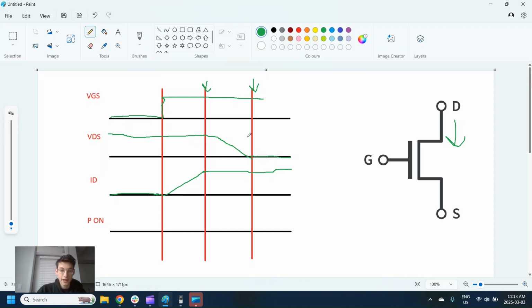So here we go. You can kind of see where the power losses might come from. Anytime we have the voltage positive and the current positive, we're going to have some power being dissipated across the switch. So every time in here, there's going to be some power loss. We're just multiplying these two to get the power losses, which will look exactly like that. So that's what it looks like, and we can walk through what the values are here.